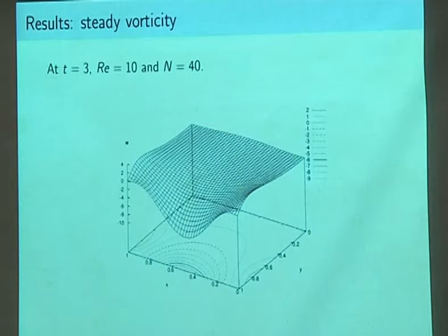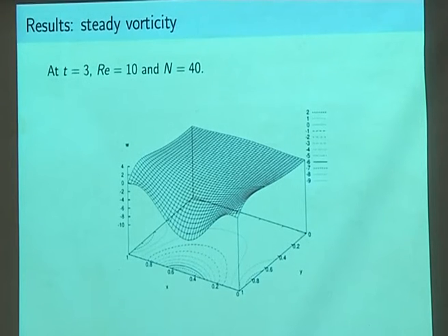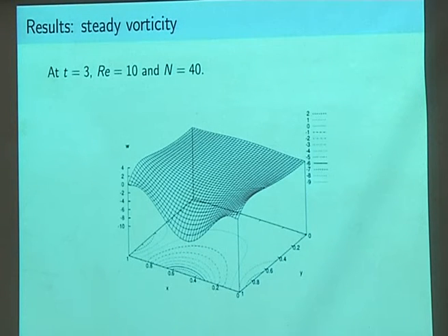Okay. The stream function is an integral of the velocity, and so it's very smooth, and nearly always the stream function is very boring. It will tell you where the flow goes, but it doesn't show you anything else. The vorticity, on the other hand, is a derivative of the velocity, and so is much more sensitive and shows you much more of what's happening. So there are much more interesting things you can see on this contour plot of the vorticity. Again, the bottom left-hand corner is the top plate going from x equals 0 to x equals 1. y goes from 0 to 1.